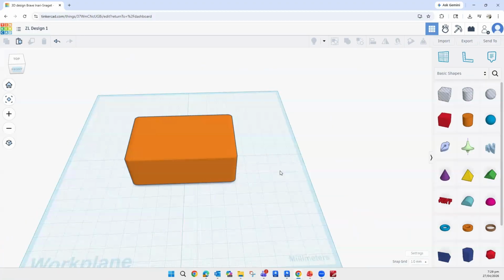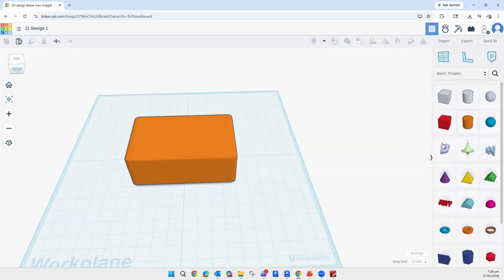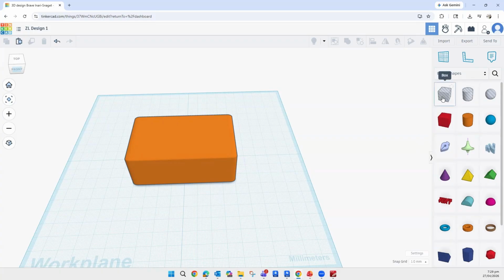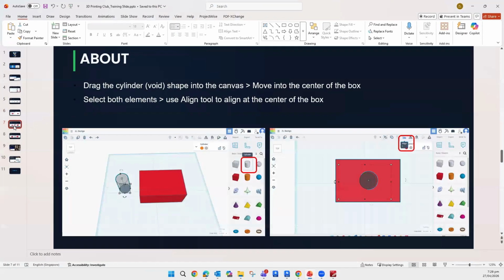Sometimes we want to create a box with an opening, right? What kind of opening do you want to create? You can select rectangular or cylinder or sphere, right? In my tutorial, what I have given to you is we will create the rectangular shape opening.